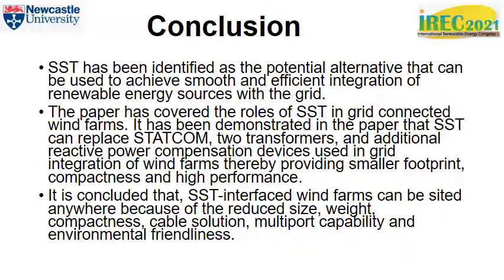It has been demonstrated in the paper that solid-state transformer can replace STATCOM, the two transformers, and additional reactive power compensation devices used in grid integration of wind farms, thereby providing smaller footprint, compactness, and high performance. It is therefore concluded that solid-state transformer interfaced wind farms can be sited anywhere because of the reduced size and weight, compactness, cable solution, multiport capability, and environmental friendliness.